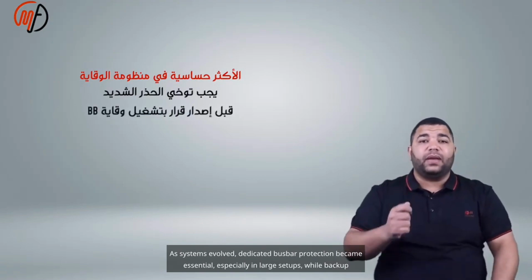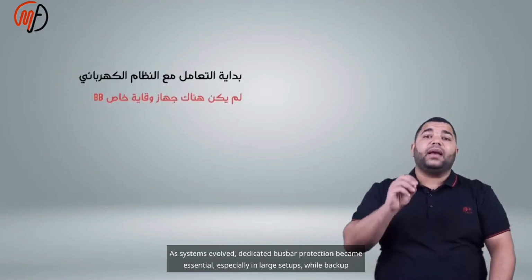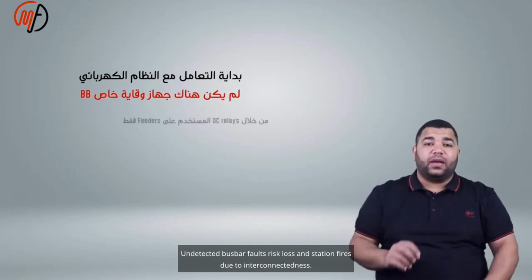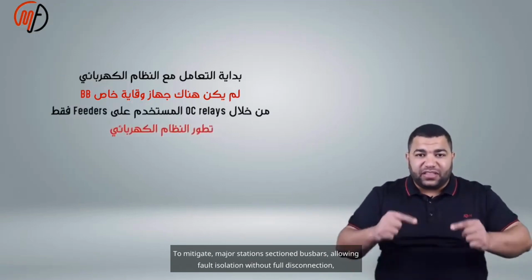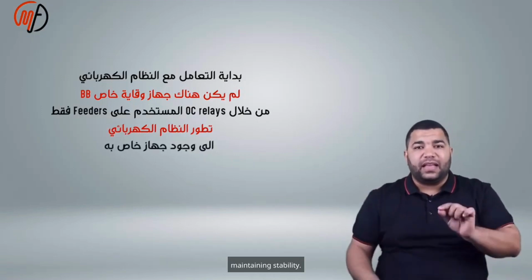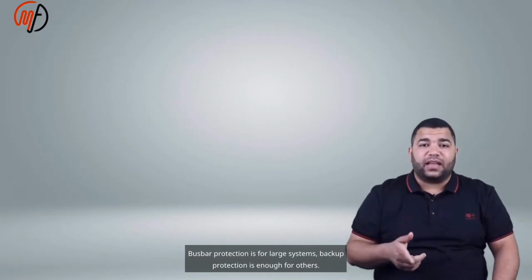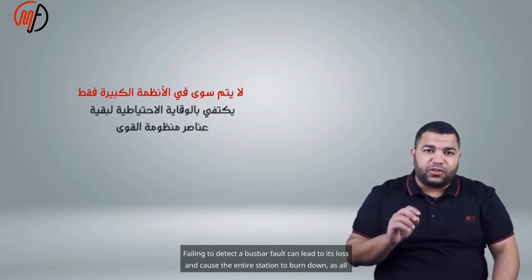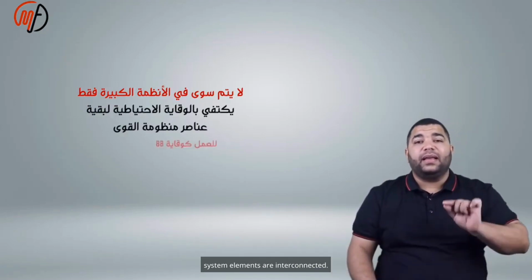As systems evolved, dedicated bus bar protection became essential, especially in large setups, while backup protection suffices elsewhere. Undetected bus bar faults risk loss and station fires due to interconnectedness. Bus bar protection is for large systems, and backup protection is enough for others. Failing to detect a bus bar fault can cause the entire station to burn down, as all system elements are interconnected.